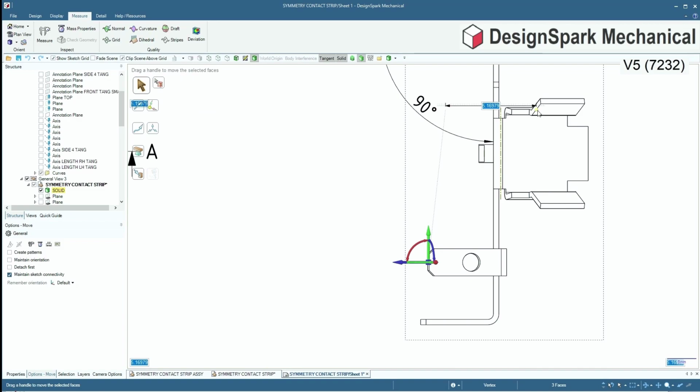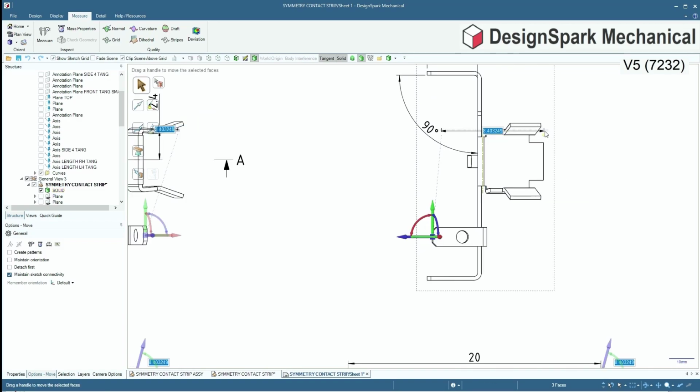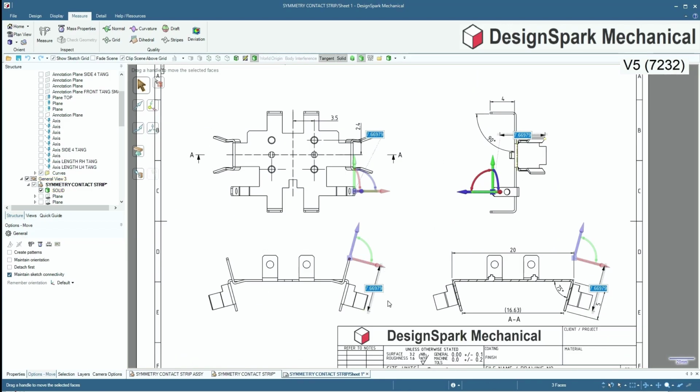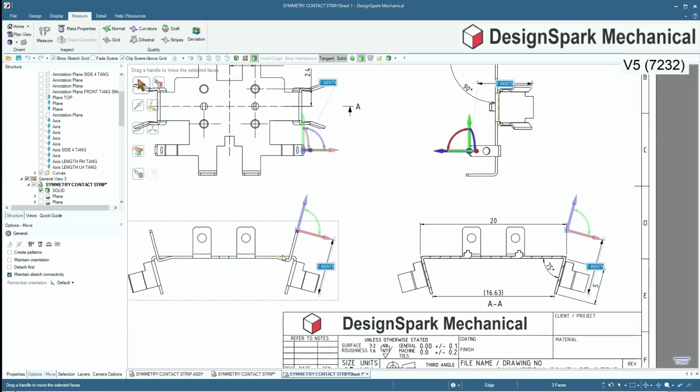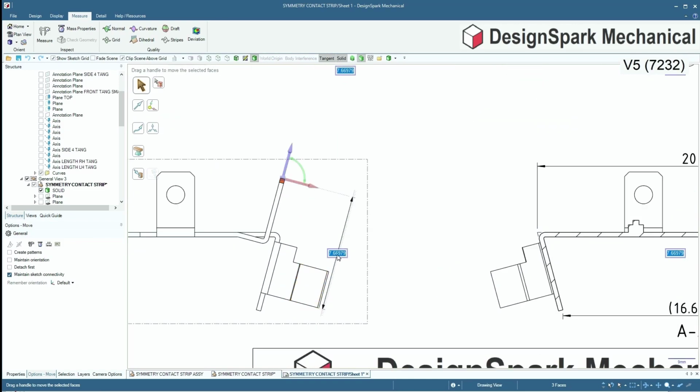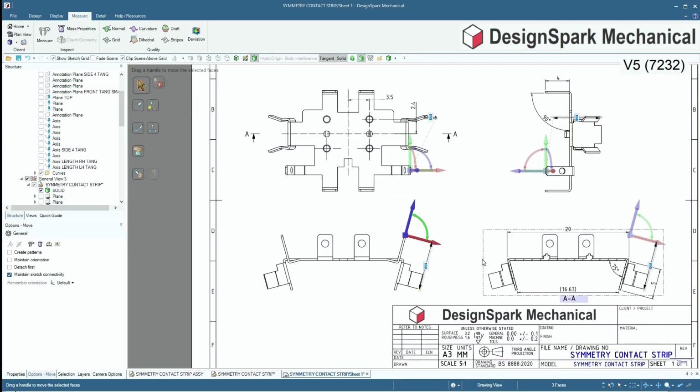For instance, there's a midpoint, an end point. So let's go to the end anyway. And you can see I've got a dimension 7.66, sounds a bit strange. But in any view, I can now select that dimension and I can, let's call it 8, for instance. That's a nice number. And there it changes to 8.